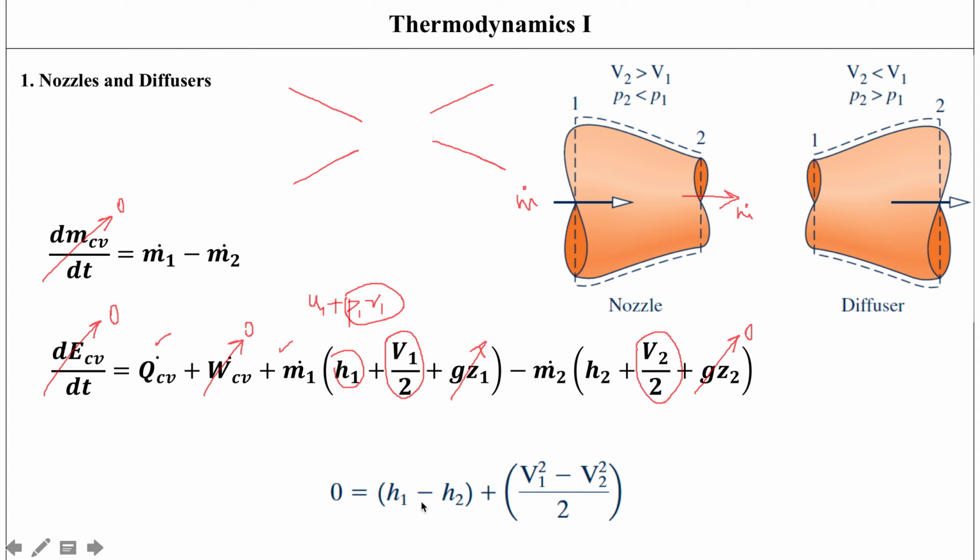So this equation is important because if, let's say, you've got enthalpy given to you at state 1, or subsection 1, then you could find out the enthalpy at section 2, or vice versa. And then this is obviously your kinetic energy changes over here. If these are small enough, then you can drop this entire term out. But again, you have to look at this on a case-by-case basis. In some problems, you may not be able to drop this term. The check for that would be if velocities are given to you, then obviously include these terms. Otherwise, just go ahead and exclude these terms if you want.